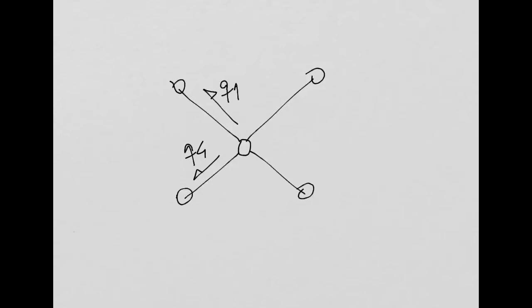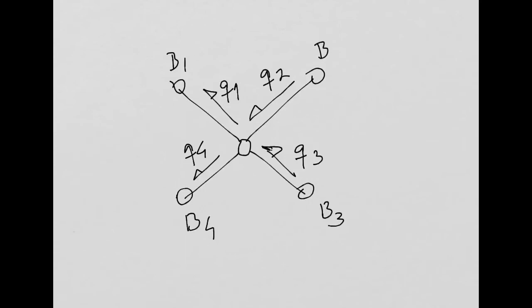So this is boom 1, this is boom 4, this is boom 3. I can have a shear flow going into the boom, Q3. I can have a shear flow here, Q2, also going into the boom. I can have all of this very generic thing. So this is going to be my boom R, the boom that I am doing the analysis, the boom that I am crossing, okay?